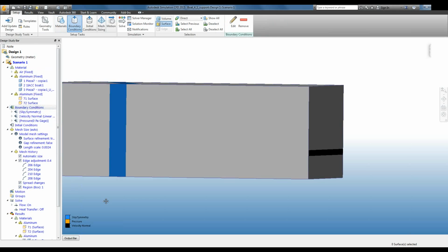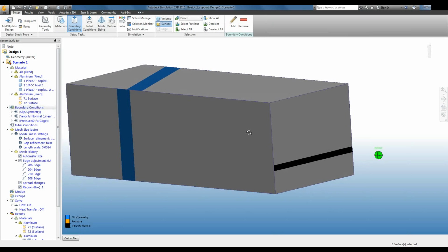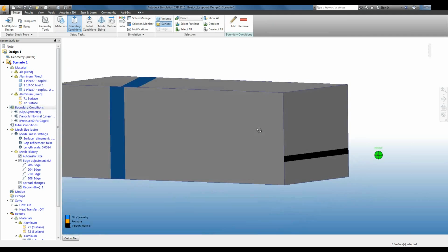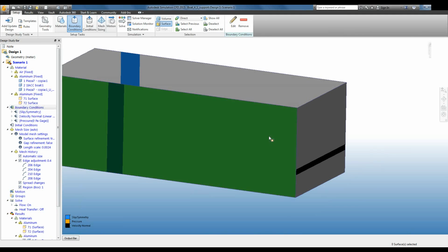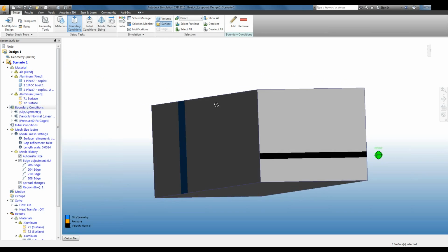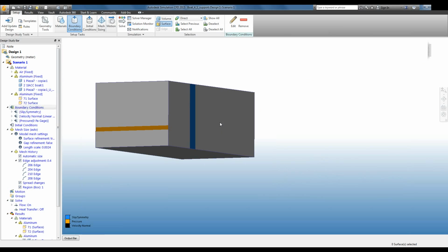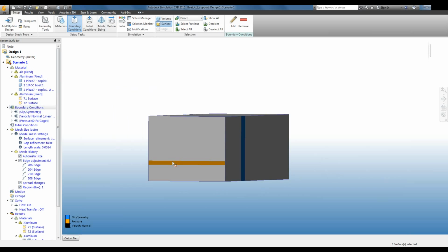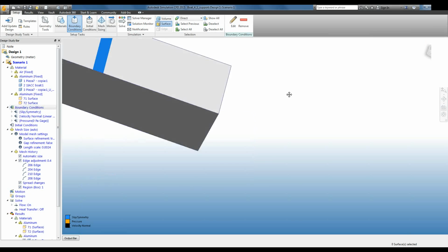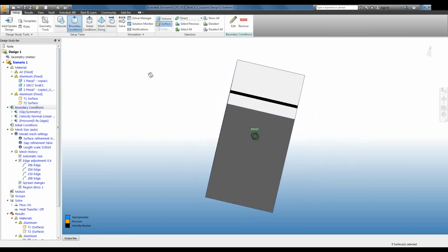Okay, on to boundary conditions. The ground plane I left alone. It'll help mimic the fact that the water-air is a friction event and that the air is not going to move as fast across the water. I applied slip on the outer walls of what basically becomes my wind tunnel. And for the back is just a straight pressure. And unfortunately my widget is affecting how I can rotate my model.